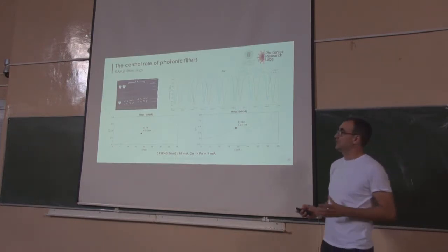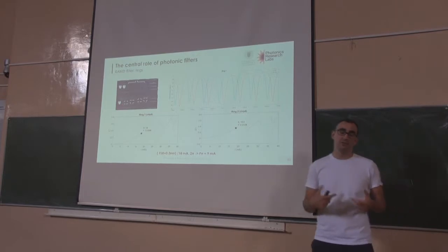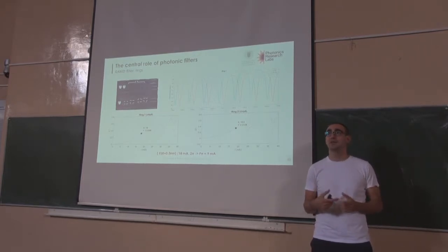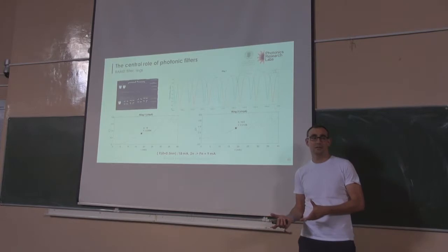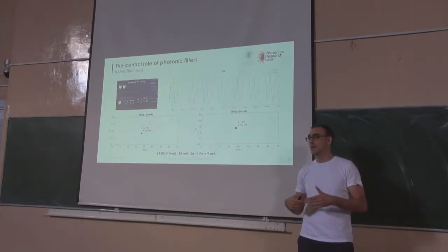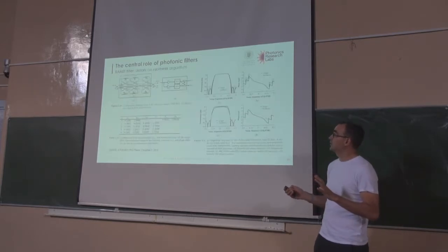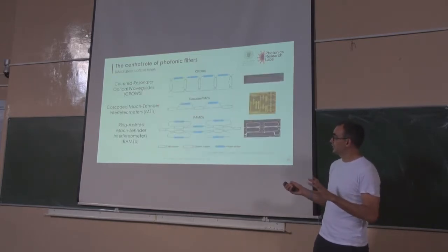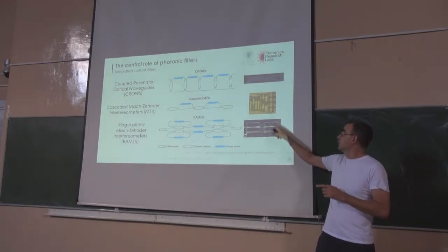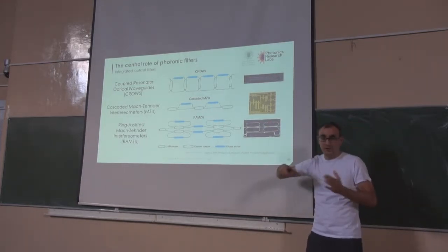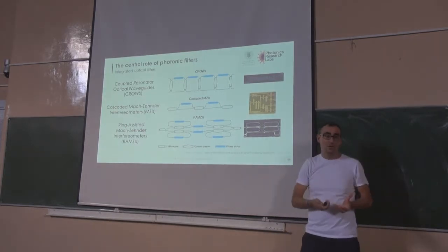And as I mentioned yesterday, those filters are reconfigurable. You can make nearly every transfer function that you wish, but they are ring-assisted Mach-Zehnder filters. They are not coupled ring resonator filters. They are not Mach-Zehnders. So actually, once you set to this architecture, once you draw your circuit, it is always this architecture. Once you draw your Mach-Zehnders, they are always Mach-Zehnders. Once you draw your rings, they are always rings.